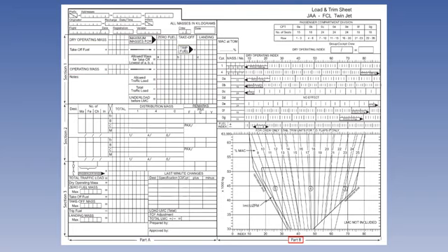The right-hand side, called Part B, shows how the position of the centre of gravity, represented by mean aerodynamic chord, alters with each change of mass. The zero fuel mass and the takeoff mass are finally plotted in the graphical envelope of Part B, and they must be within the operational limits.